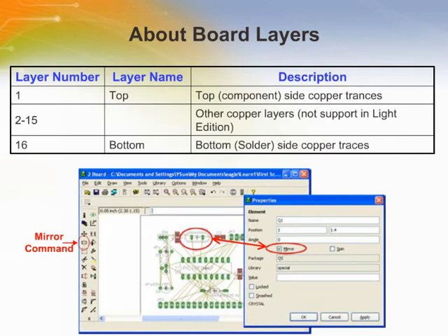A standard printed circuit board consists of several layers of fiberglass pressed together, with places for chips and connections between them called traces. When placing traces, pads, vias, and even text descriptions, it is important to place it in the appropriate layer. The table shows some of the more important layers.